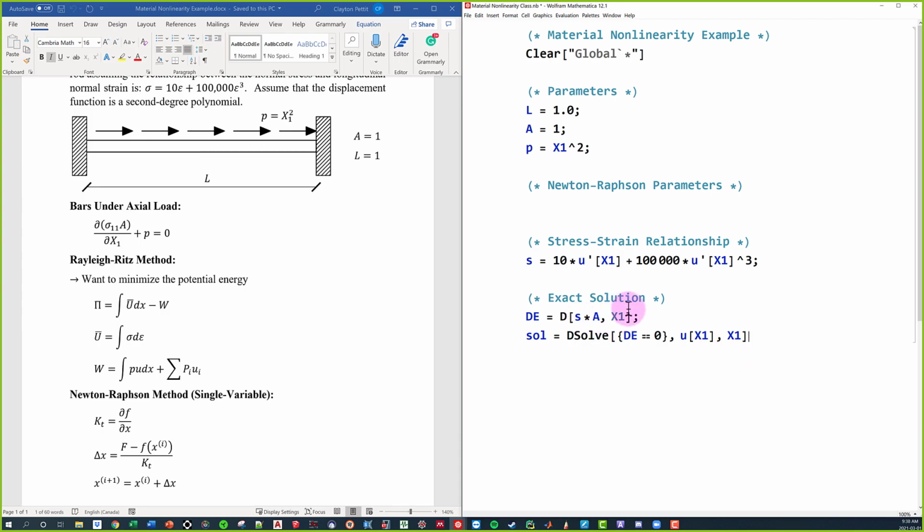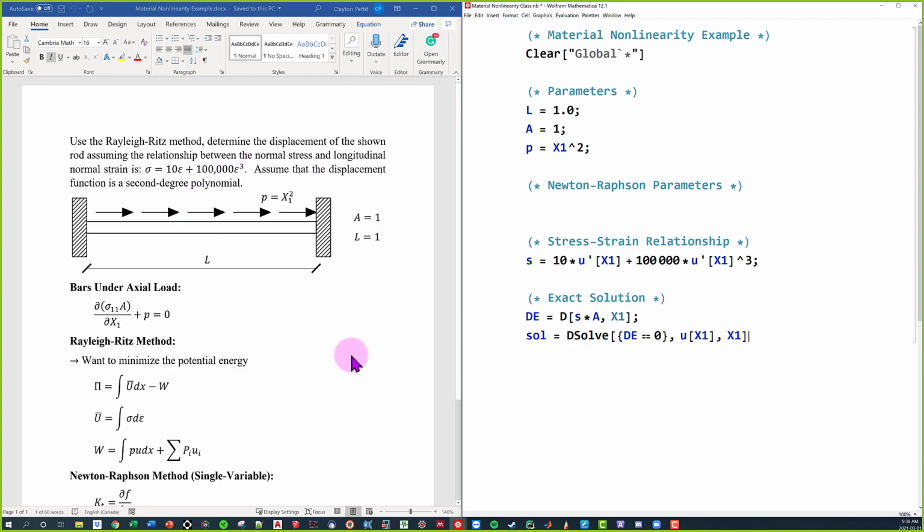You guys are on your game. Boundary conditions. Exactly. So if we were to do this, it would still solve it, but we're going to have two c constants. How do we solve those c constants? Well, we implement the boundary conditions. So if this is my beam right here, what are going to be my two boundary conditions? What do you guys think? Remember, I'm solving everything in terms of displacement. So what are going to be my two boundary conditions for this beam?